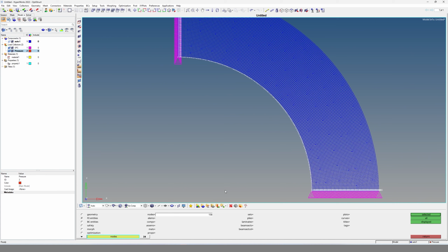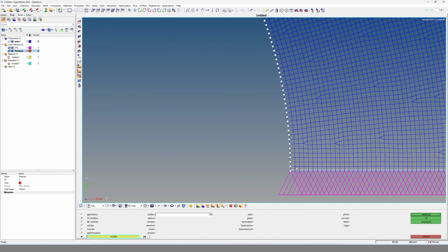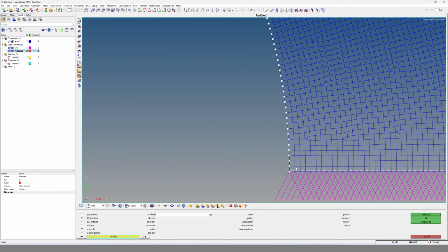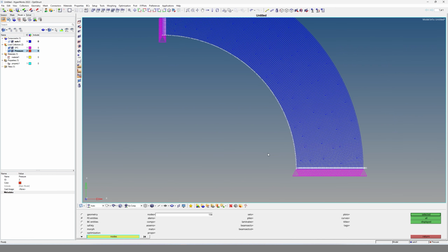Once we get the number of nodes, we can divide the total force by the number of nodes. That will yield the individual force that should be applied at each node. However, what we have is a pressure, so we need to transform the pressure into force by multiplying the pressure times area. In this case, a quarter of the total area.